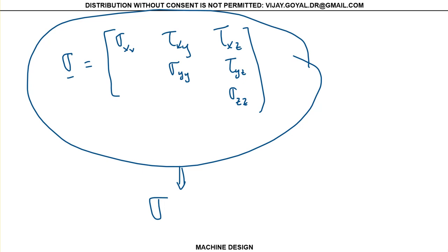And how do we know if something is going to have failure? Well, we remember we had two cases. First of all, don't forget what we started with. We have your nd, that's the design factor. Okay, that design factor is multiplied to your load. So your new load will be your design factor times that load.